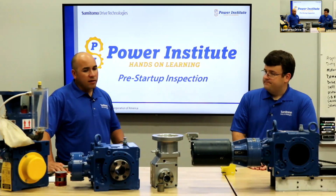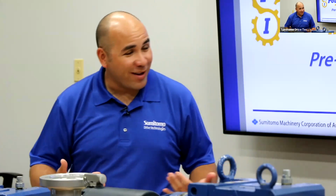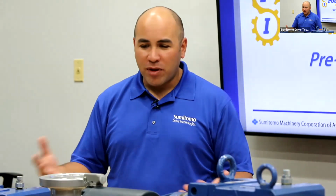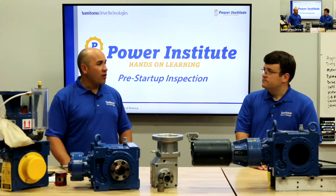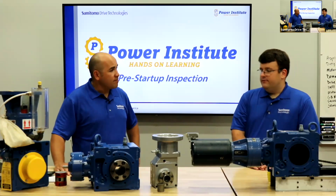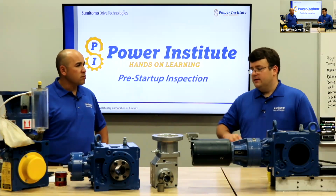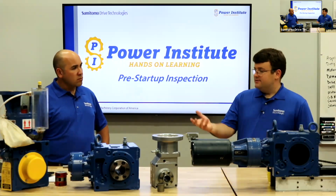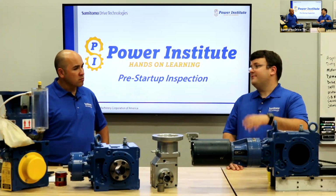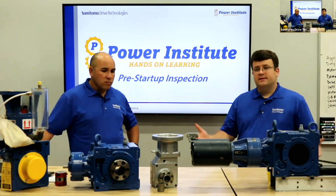And I know we're talking a lot about the products we've got here in front of us, which obviously are our products. But for other manufacturers, a lot of the same stuff that you're talking about applies, whether it's bushings or keyed hollow bores or the other equipment that's shipped with it, right? Right. So we follow industry standard in general as far as tolerances go and shaft fits and things like that. The only thing that's 100% standard is keyed hollow bore. If you have a certain size shaft, the key that goes with it is exactly the same, no matter who you ordered it from.